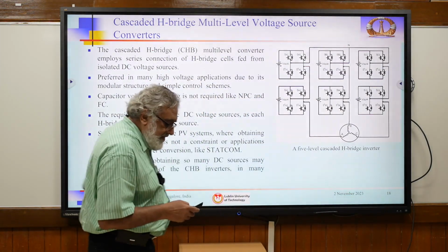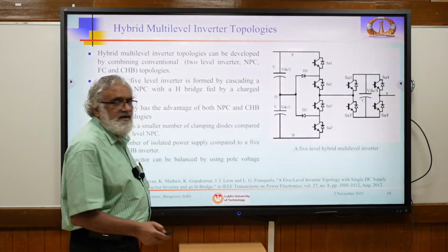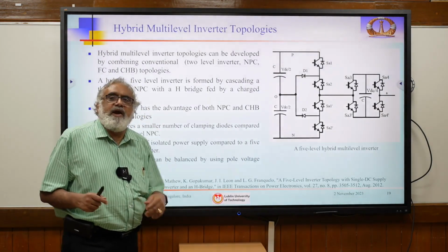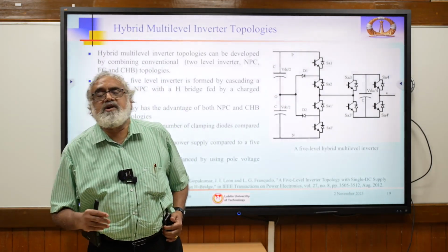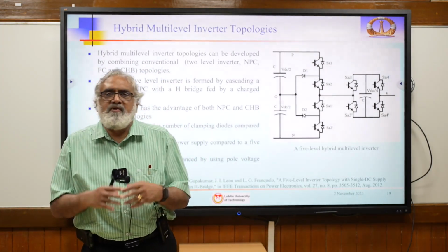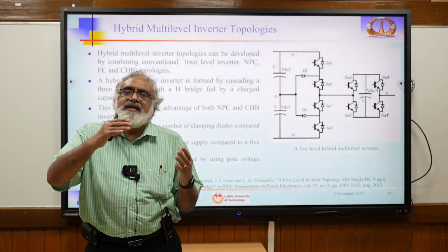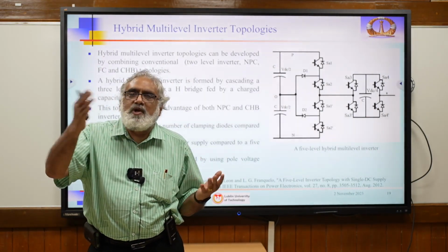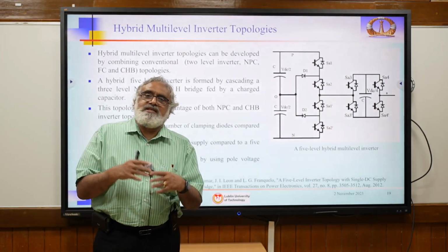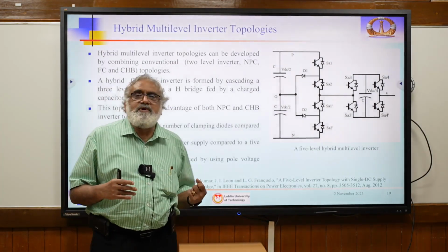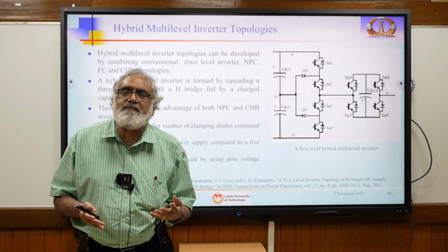Then we were thinking, why do you require more number of power supplies? You want to get a stepped waveform. Why do you require a stepped waveform? With all the stepped waveform, still the maximum voltage range is within the two-level inverter, 0 to 0.637. That is, the fundamental voltage is still the same. Why do you require stepped voltage? So that the harmonics can be suppressed.